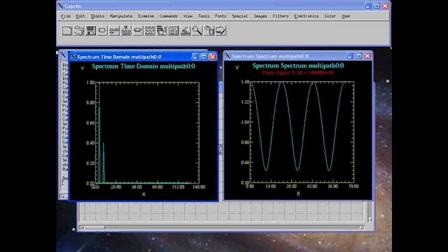You'll notice that we have the bulk delay and we also have the delayed multipath with a gain of course 0.4, and you'll notice that in the frequency domain we have the basic peaks and valleys of a multipath channel with a single ray of multipath, and the distance between these minimums or valleys here, which are actually very bad for communication because these actually wipe out the signals. If for example we have energy and these are a carrier within these regions, they would actually be fully attenuated.